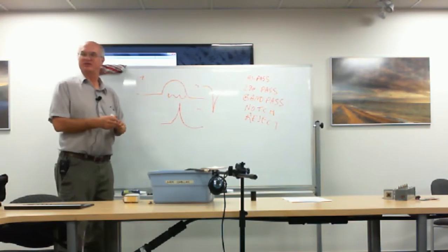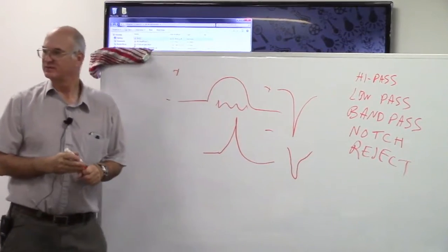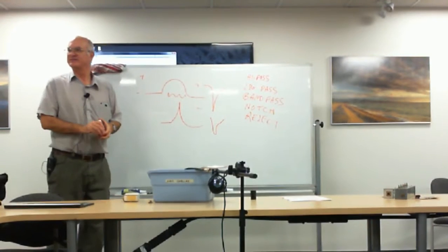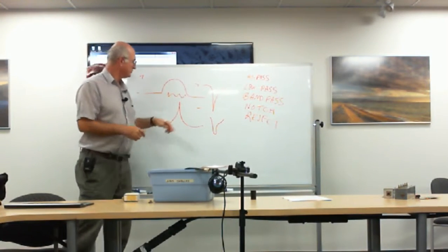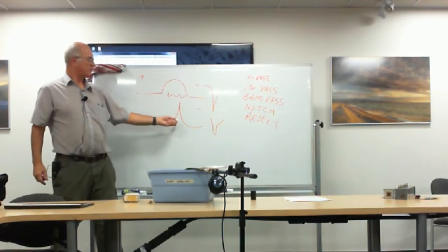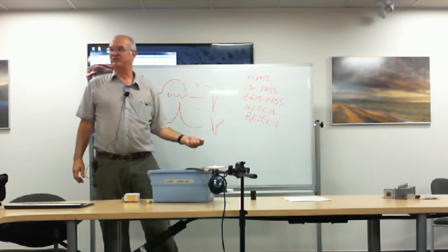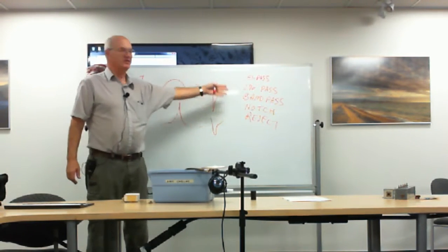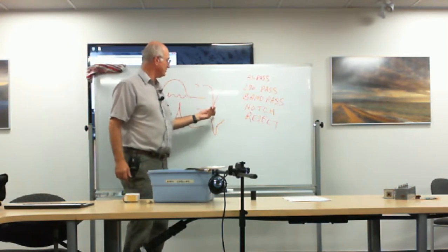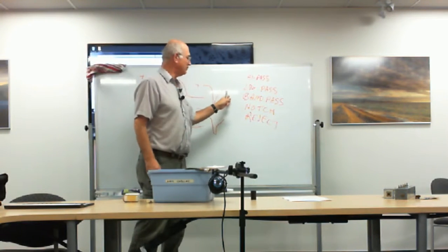But being coax, of course, it's not going to be as tight as that. It's probably going to be more like this. But as long as it gets the frequency I'm after and it's far enough away from what I want to receive, I don't care. It works. Simple and cheap. This one's the opposite. Blocks them all until it gets to the one it wants. Now, the sharper the filters, the more they cost. They get more complicated. You'd use it in specific instances if you had to. Usually, you'd try to use a simple capacitor filter type thing. But in special cases, in commercial stuff, they need to use sharper filters because they have other frequencies they want to pass that are close by.